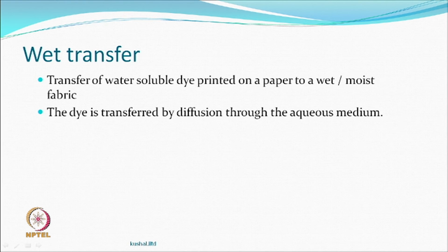So, although you can say, well, I have not added alkali, I will add alkali later, that means the fixation step will be a different step. First is just wet diffusion and then fixation. So, you can work around it, but again, as I said, it goes through the aqueous medium. So, there will be some dissolution happening and it has to be very controlled dissolution, so that as it is getting transferred, it goes directly to the place where the color is supposed to go and not anywhere else. Otherwise, you will obviously not get the same effect of a photographic image.